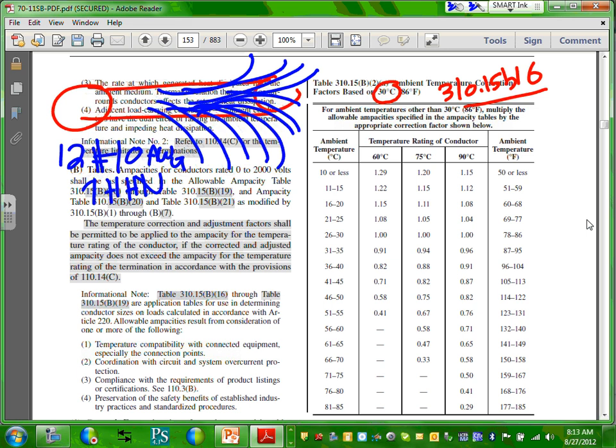All these conductors are branch circuits feeding machines. All of them are 3-phase, carrying current. 12 will give you 4 circuits, 3-phase each, going to the machines and feeding them. All in one conduit, 12 of them, THHN. And I want to see how much current THHN can carry under these circumstances.